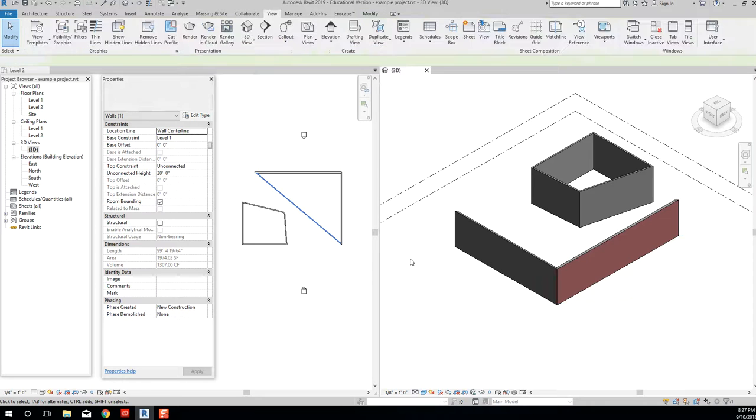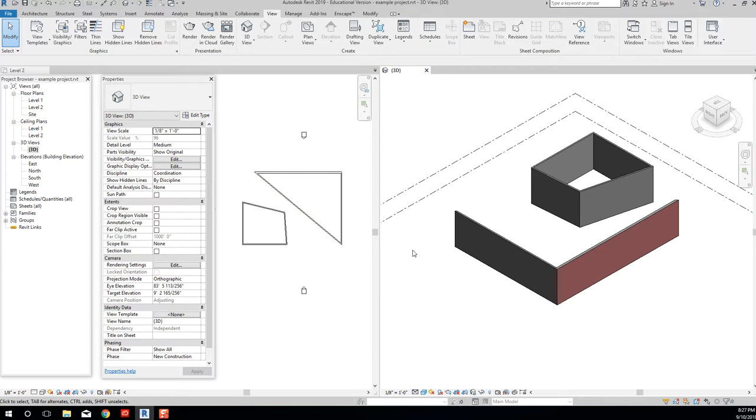So I guess my point with this is that the views in Revit are independent, and things can be manipulated visually independently on differing views, okay? Now that doesn't mean that I've deleted the wall here and not here. It just means that I've turned it off. Visually, I can't see it in this view, but that visual style that I've applied here doesn't apply to every other view in the model, okay?